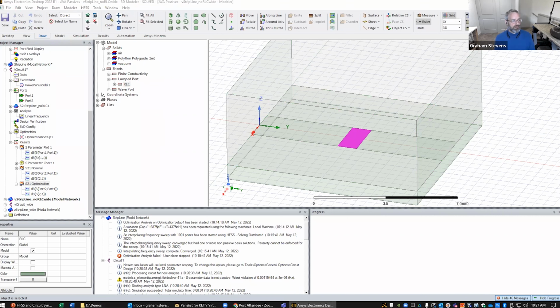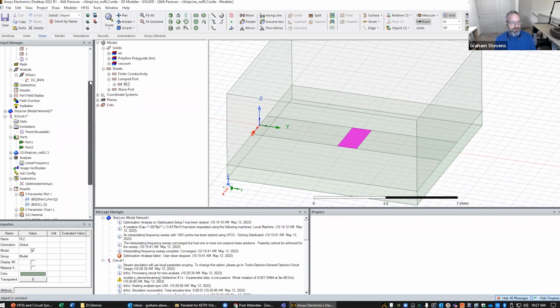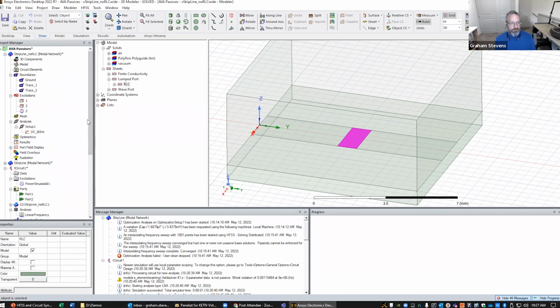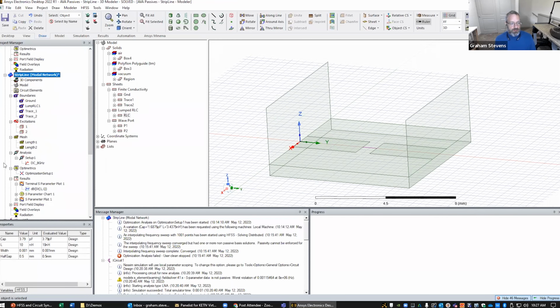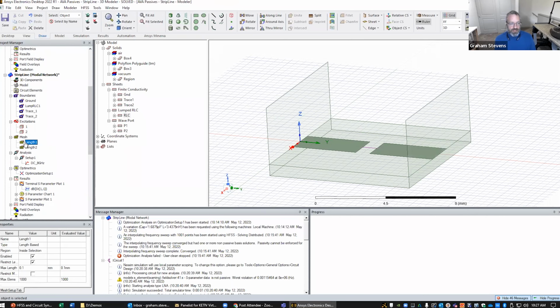Does that make sense? In terms of the width here as well, when I have a much thinner region, it really helps within HFSS to create these mesh assignments here, where I increase the amount of mesh within this small area, to converge to your solution much faster.